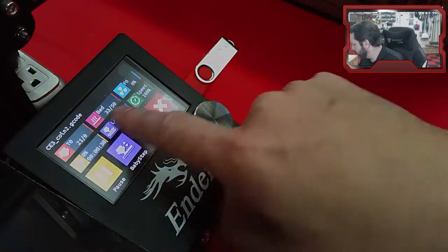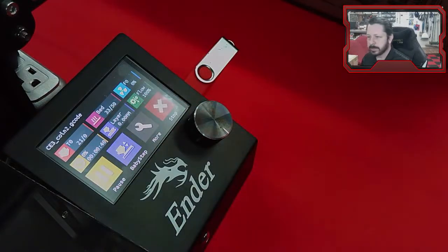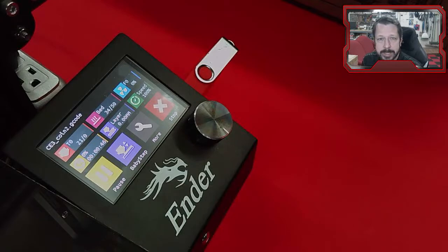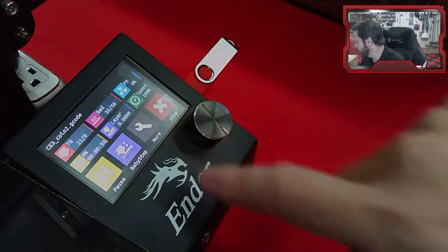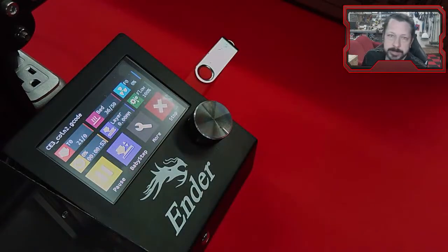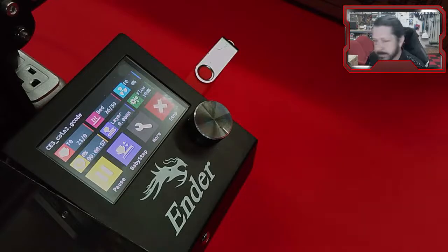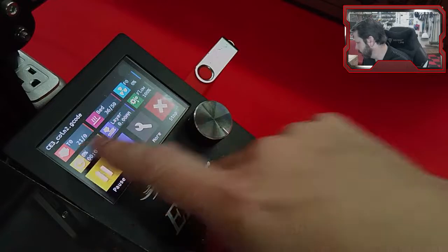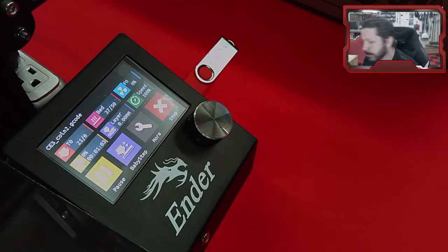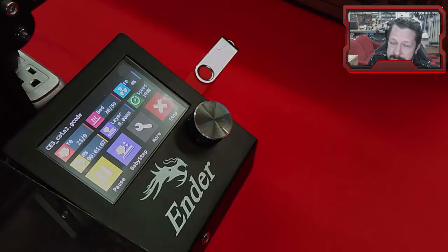But it's going to have information like the bed. This bed on the printer heats up. You don't have to heat up the bed for PLA, but it helps the parts stick down a little bit better. So it's heating up to 50 degrees. These are all in Celsius. So 50 degrees Fahrenheit doesn't seem like much, but 50 degrees Celsius, the bed gets kind of warm. The nozzle, once the bed gets up to temperature, the way the code is written, this nozzle will start heating up. It's going to heat up probably to 220 degrees Celsius. So it gets very hot.